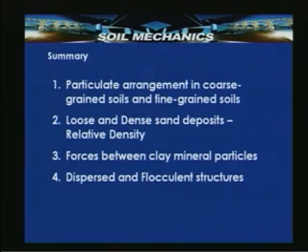So, in this lecture, we have seen the particulate arrangement in coarse grained soils and fine grained soils, and we said that different types are possible as per the classification of Terzaghi and Casagrande: single grained, honeycomb, and flocculated or dispersed. We also discussed loose and dense sand deposits.